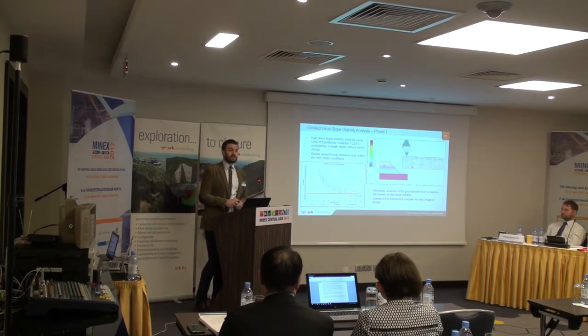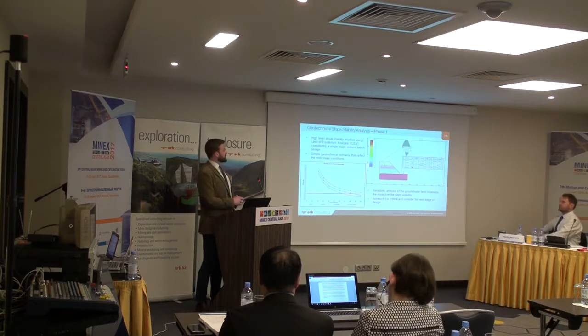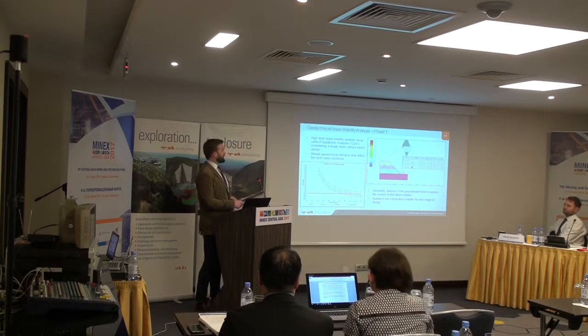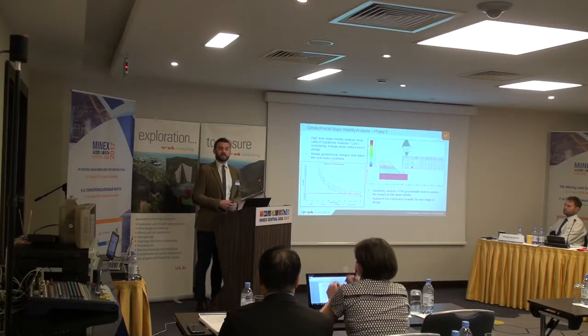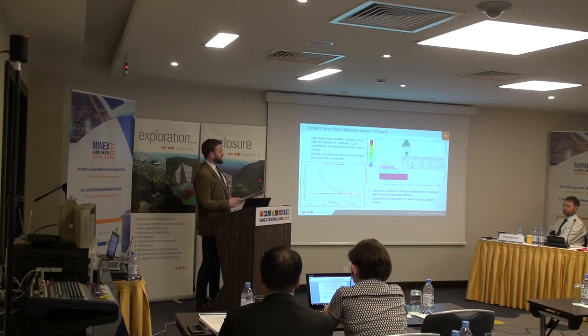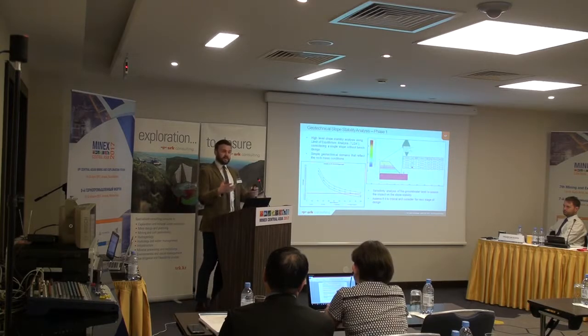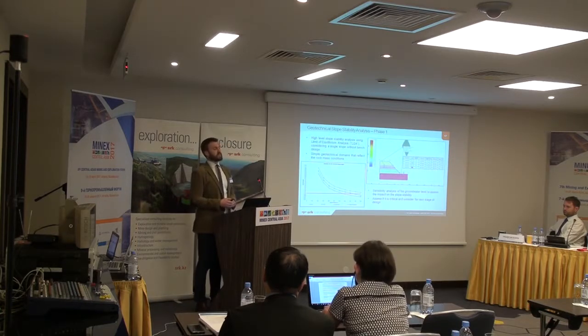For the phase 1 geotechnical slope stability analysis, we usually do a high-level slope stability analysis using limit of equilibrium. Sometimes we can use more detailed numerical modelling packages that do finite element, but more often than not, the LEA is sufficient for a deposit. And we develop simple geotechnical domains that reflect the rock mass conditions. And usually what we try and understand here is the impact of the groundwater on the pit slope and whether it is critical to the pit slope design.